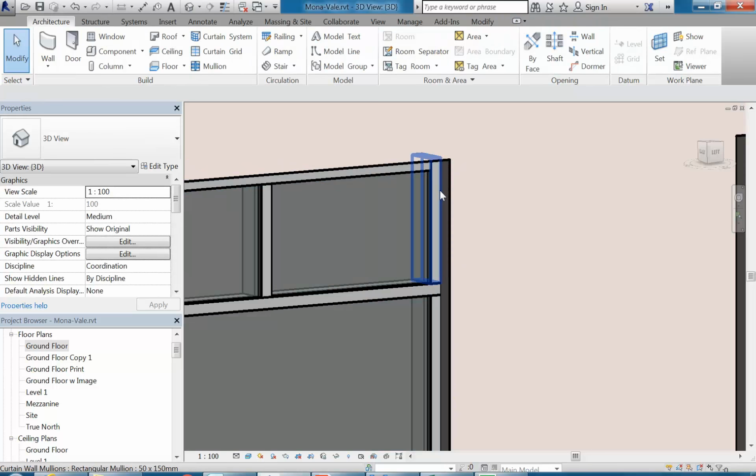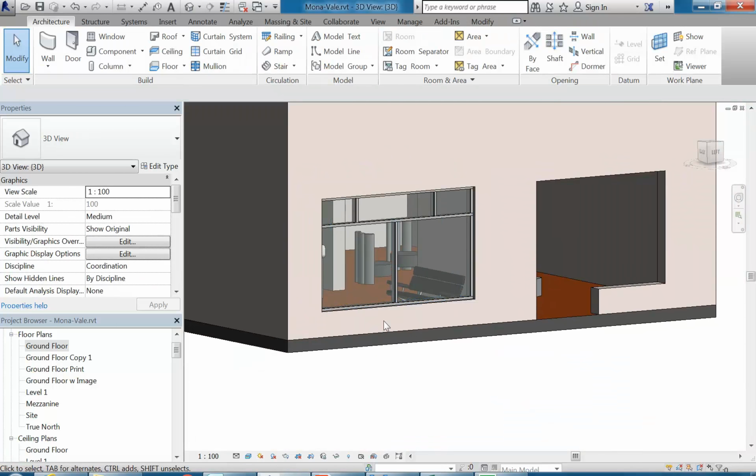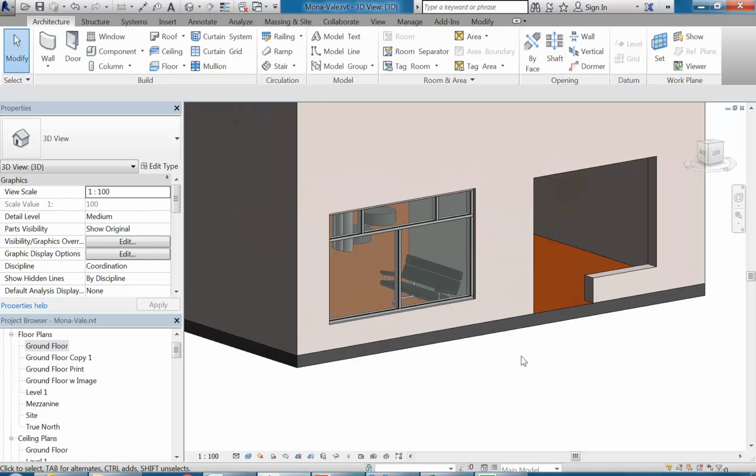And you'll see later there are automatic ways of doing all of this. If you've got a huge wall with hundreds of mullions, you don't want to have to go and select each one. So there are ways of doing it en masse. So I shouldn't do my whole warehouse with lots of little windows this way. That doesn't work very well. No, that's right. What you do is set up not a system, but you set up a wall type. You can definitely copy and paste, yep. But you can also make an automatic wall so that it'll always have the same spacing between your mullions and have all of that set up in advance.